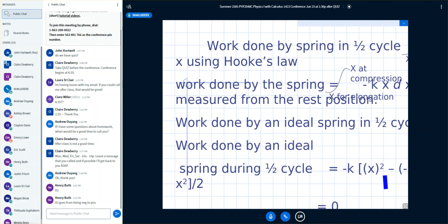This equation here, minus mgs sine of 30 degrees, is the repeated equation I was talking about. And isolating then the terms in S, solving for S, here's the S right in here. I got about 1.32 meters. So that's really a solution to the previous equation for my example of a 3A.